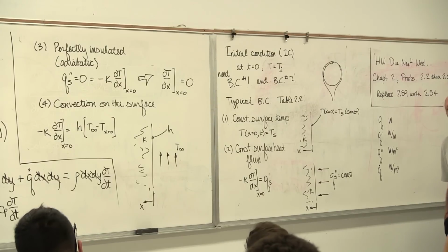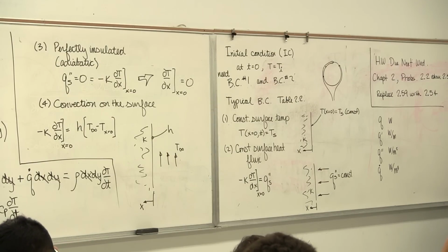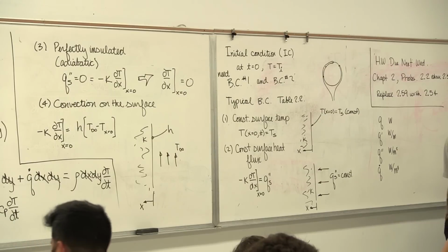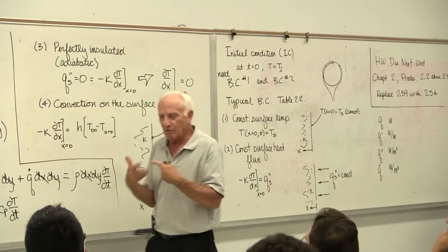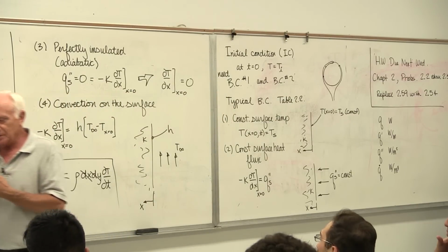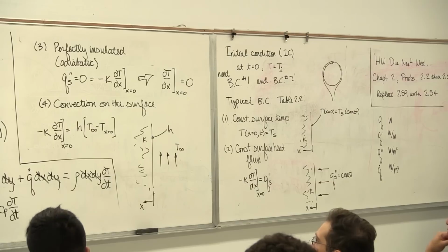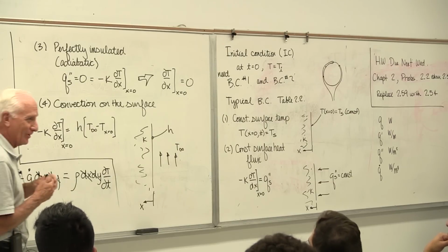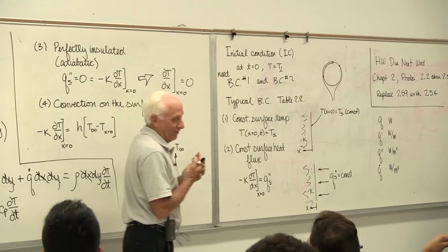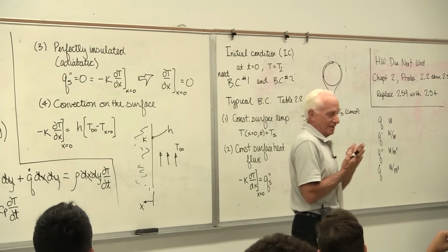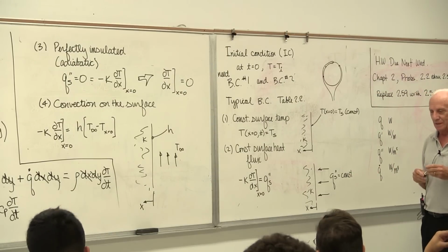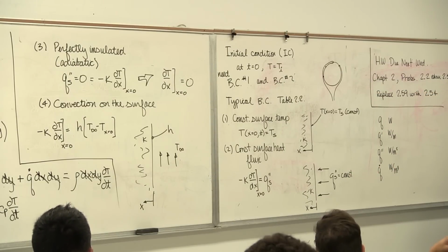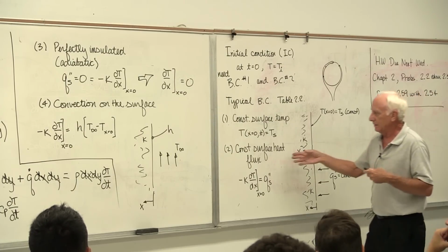At night, there's oil in there. Or you could put the oil back into a big storage reservoir, or leave the oil in the pipes, and the pipes are wrapped with the electric heating blanket. And they trickle a little bit of power through it, just enough to keep the oil warm, because in the morning, when you throw that pump switch on, you don't want cold oil, very viscous. Your pump might burn out. So you heat the oil up a little bit so that when you throw that pump switch, the oil is less viscous. So you wrap it in a blanket like that.